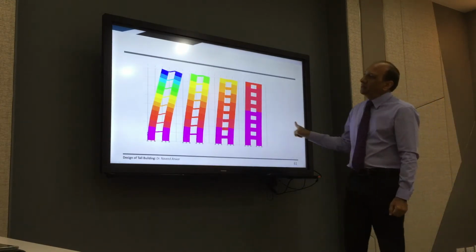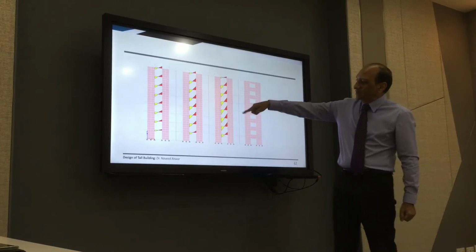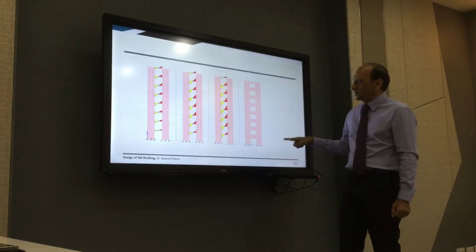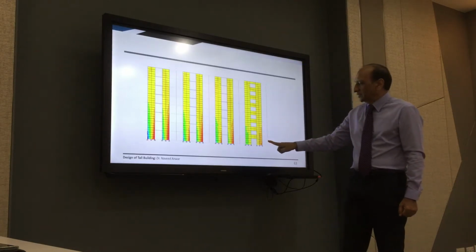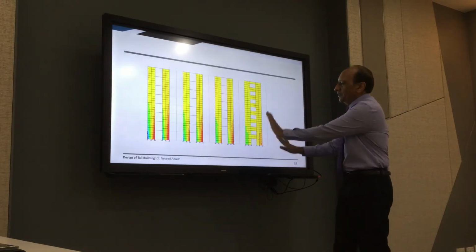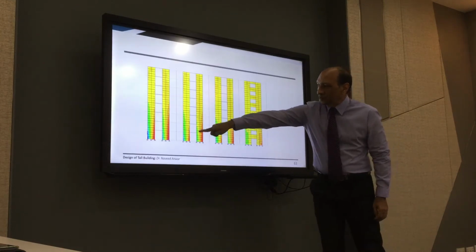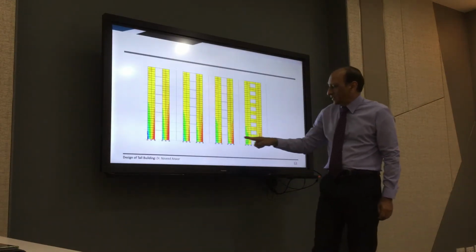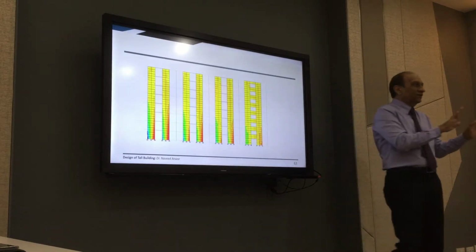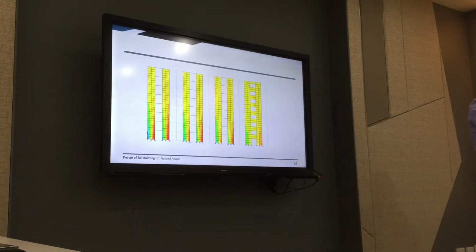So in the link beam design, you can see from here, large shear as we increase the sizes. Axial stress is changing in walls. Here becoming almost tension compression. Here local bending. So this is pure bending of the tension compression. Here tension compression. So you have moved the local bending of each wall to axial stresses in the two legs.